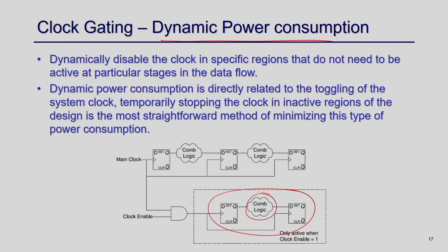So there is a toggle, and as a result this circuit is also consuming more power. What can I do? I can gate the clock, so I can have a clock enable. This is my clock signal. I can have a controller which generates this enable signal as 0 for, say, the example I am giving, cycles 11 to 25. As a result your clock will remain 0, and the content of this register will not change, because you do not get any positive clock edge.